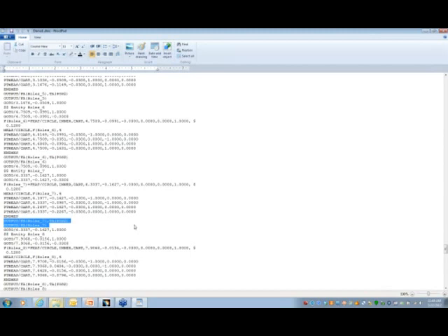There's really no change. As far as custom reporting, we have some other CMM add-on tools that are Excel-based that we could talk about, so we could take the CMM report and go into Excel. We can do some best fitting, some SPC, stuff like that. But as far as this tool, it just creates the native language that's going to create the report just like you're doing today. Okay, very good.